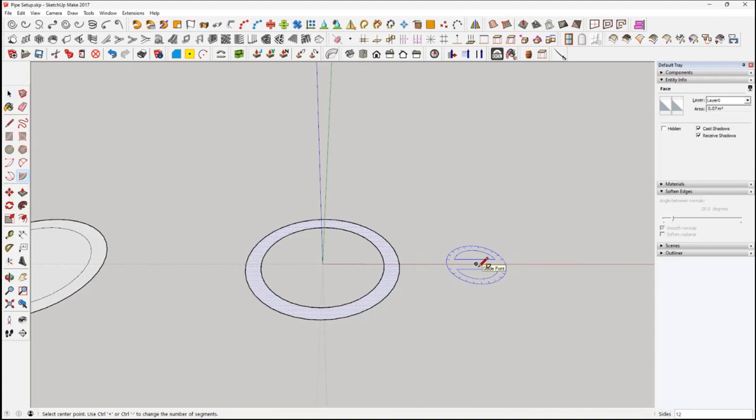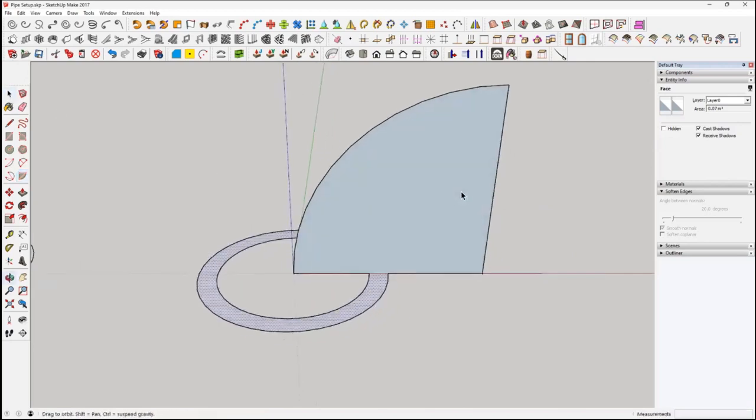So if you press the left arrow, changes it to the green one. Click on the end of the point we made, and then go to the centre, or actually press the red, and that'll constrain it. You can't go off centre then, and it'll click to the origin. So we click there, and we start drawing our arc. Now, choice, you can have whatever you like. We'll do a 90-degree elbow, so we tap in 90, bottom right-hand corner, 90, or press enter. So we know that's going to sweep round.